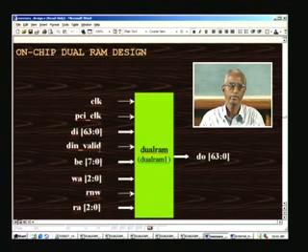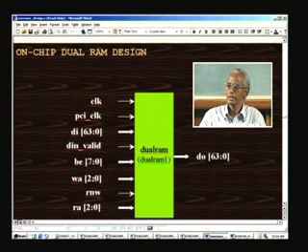That is the implication there, and so in order to write here, we need only a 3 bit write address, and this corresponds to 8 such locations, and each location is 64 bits in width.